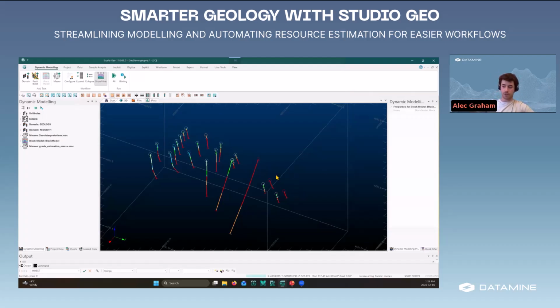Whenever we're retaining those pre-existing drill holes, we're not going to be losing any of that data. However, if we are bringing our drill holes in a different way, like using a script or something else, we're going to be overwriting that pre-existing drill hole every time. So it's really important that we save that data. This macro here is basically just extracting all of the important data from our drill holes and saving it as a separate file, so that whenever we import new drill hole data, we can just append this back onto it. And that way our interpretations will just be saved every single time.